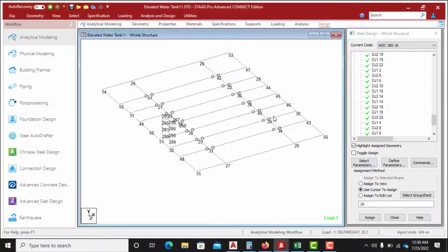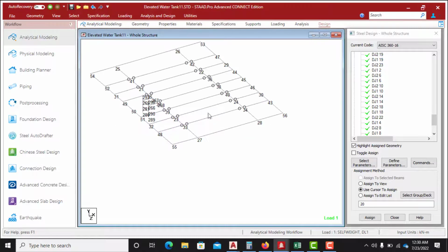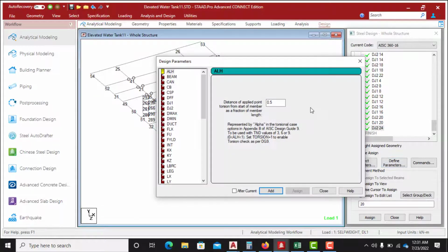I'll do that for this one at the middle. If this one passes deflection check, this one will pass. Also do it for this center one that has more load. I'll do it for them. Then I will do for this main beam and that main beam. If they pass, then I'm okay, I'm good to go. So I also click here.